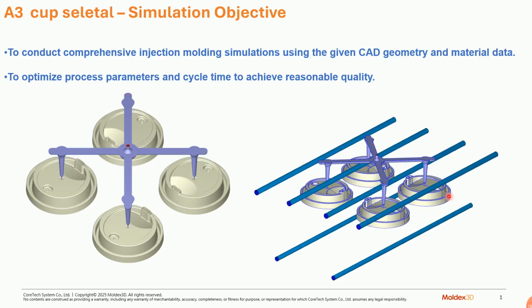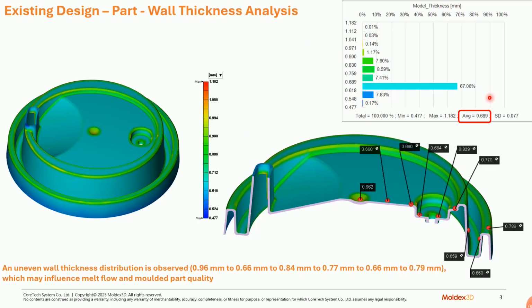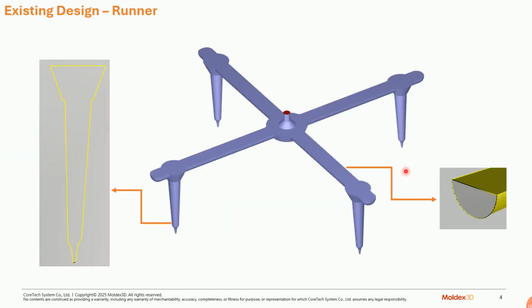This is the runner cooling channel layout, and this is the sectional view of the component, where you can see this profile. Further, the wall thickness of the product is a minimum of 0.5 millimeter and a maximum of 1.1 millimeter. Quite importantly, throughout the component the wall thickness distribution is not consistent. Instead, we can see variable wall thickness. Of course, with variable wall thickness there is a great possibility of some molding defects, but still, let me handle them with the mold test simulation.